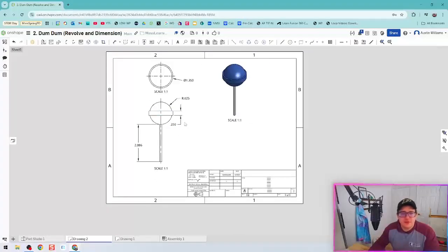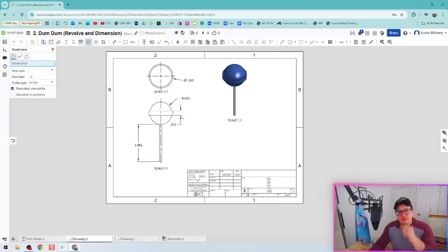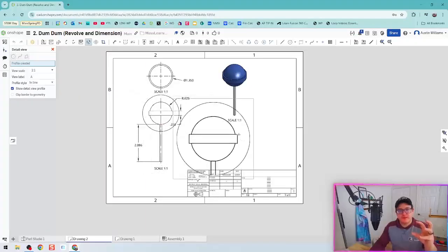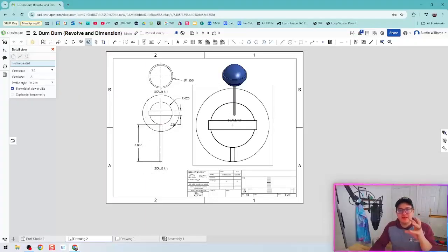Alrighty, I'm sure there are other dimensions I could throw in here. However, I do want to show one more. Hop on with me for just a few more moments, and that is going to be section view and detail view. When we look at detail view, let's say for example, I need to look at information that is too compact for the drawing we're looking at. Under detail view, the first click is what you're going to be looking at closer. The second click is how big of an area we're looking at. And then it'll blow up that view for a detailed view.